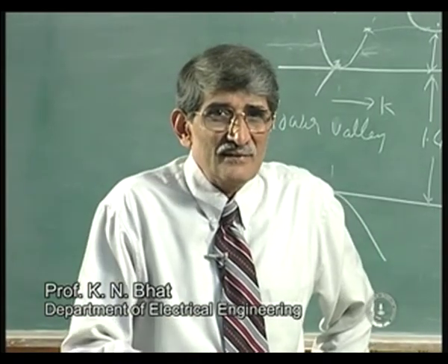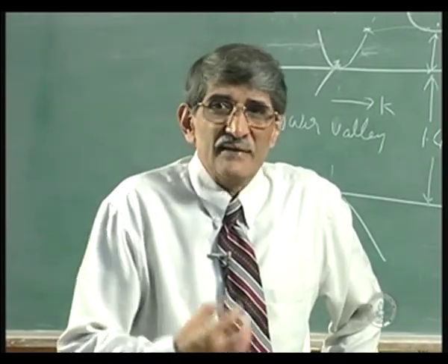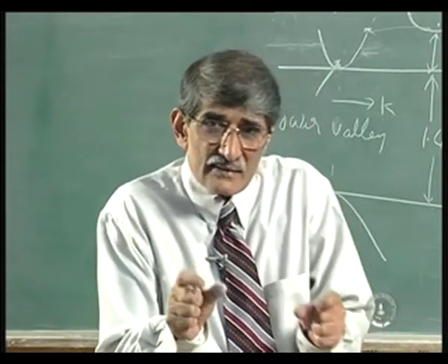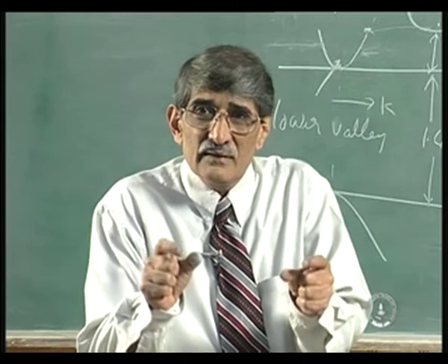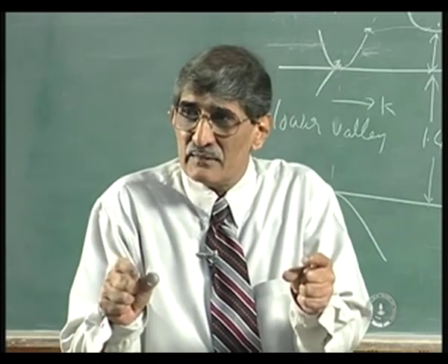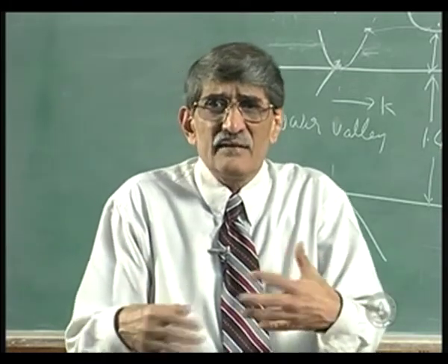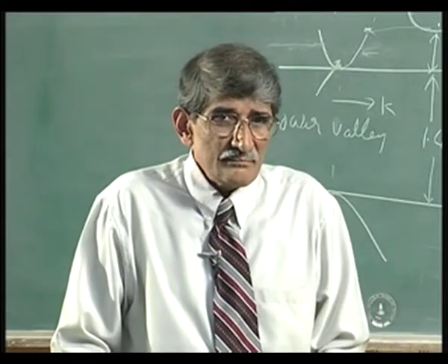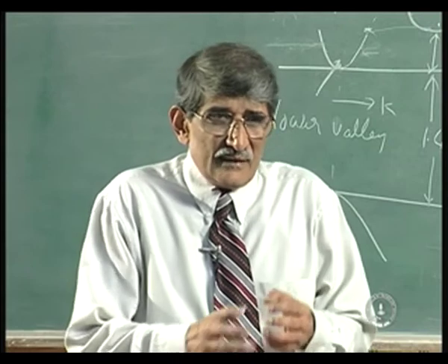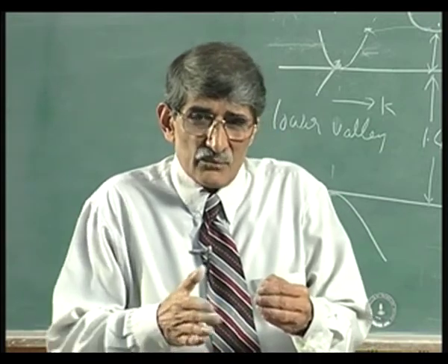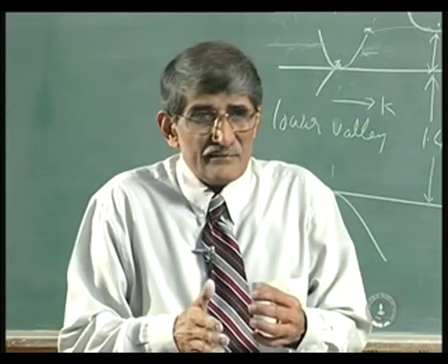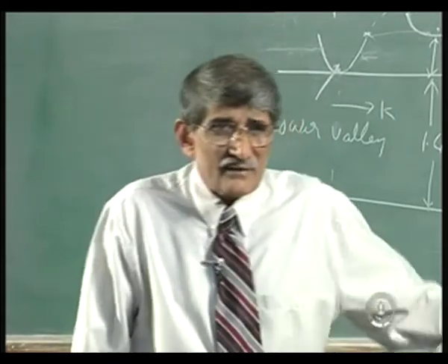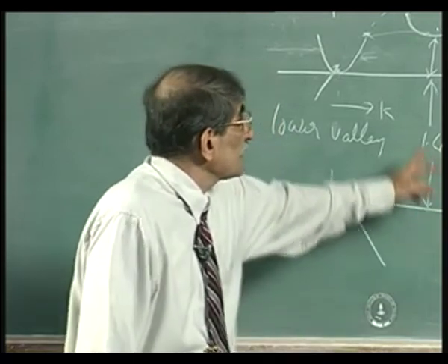All that happens is the mode of transport is slightly different, because the energy acquired is so much that the extra field that comes from the plus charge on gallium and minus charge on arsenic is no more effective, because the velocity is so high here. If there is a plus charge, the electron tends to move in that direction, but if the velocity is high, it will just not see that effect. That is a simple-minded thinking on that.